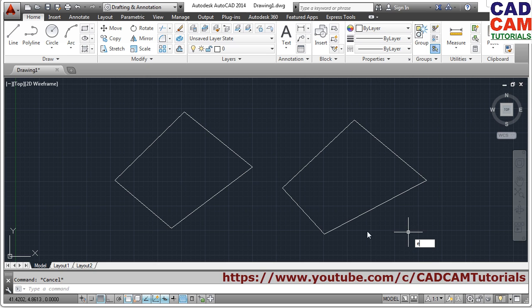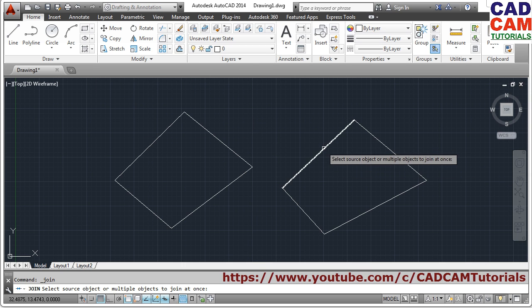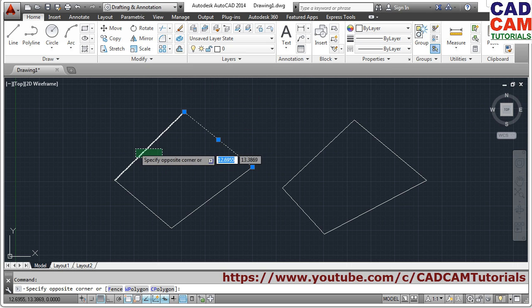You can convert a regular line into a polyline by using the join command. If you use the join command, select all the objects and press enter, and they will be converted into a polyline. Or you can break a polyline and convert it into simple lines using the explode command. Click on explode, select the polyline and press enter, so it will be converted into simple lines.